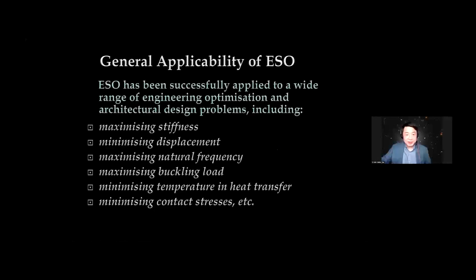When you're trying to find the most efficient shape, it really depends on what material you use. Some materials are more suitable for compression, like concrete, stone, or masonry, and other structures are more suitable for tension, such as cables, membrane, or fabric. So if you're using materials like steel cables, you want your final shape to be in tension.